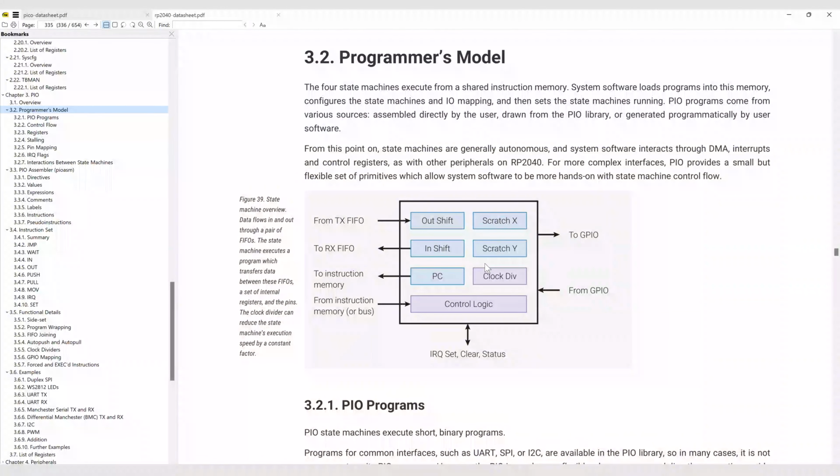First of all, the FIFOs allow you to send data from a CPU into this part. That's an essential part of moving data: you put data into it and then something happens to it. In our example with LEDs, we push the colors of the LEDs into the PIO, and then the PIO program takes those bytes and turns them into the serial bit stream that the LED needs.